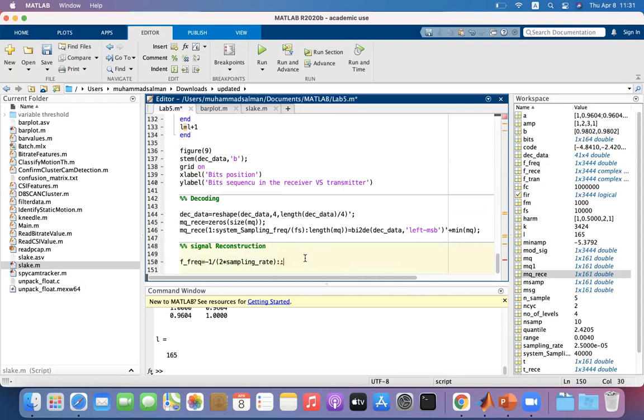Let's not make the offset, and then I'm going up to plus this one, right? So I'm starting from minus fs by 2 to plus fs by 2, and now I have to put an offset here. So 1 divided by the sampling rate times the length of t, because we have to align it exactly with the time, right? So it should be like that.